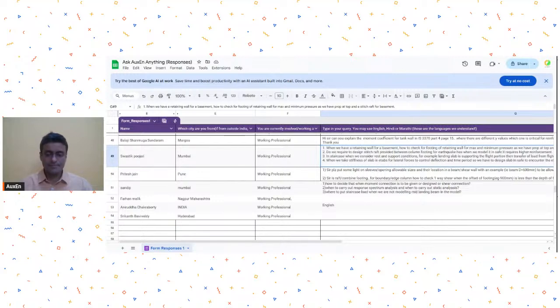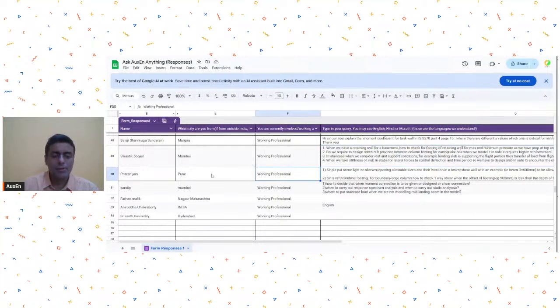Okay. Usually a 150 thick slab with two layers of reinforcement at top and bottom. Our code says it is good enough to take all sorts of lateral loads and safely transfer them to the vertical element. Just in the chord and collector region, you have to be a little bit more careful. Otherwise, you don't have to think much about the diaphragm design. Okay,